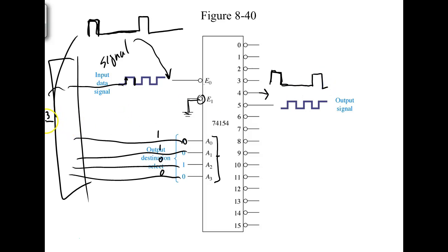So what we're doing is we're taking 3, we send all the wires, right? But how many wires are we using? We're using 5 wires, and I can multiplex 16 signals on 5 wires. So what did I do? I just saved 11 wires. So you see multiplexing used a lot because it saves media, right? You understand that?